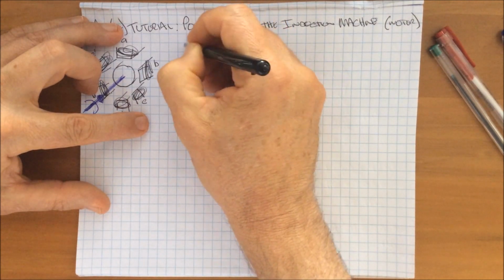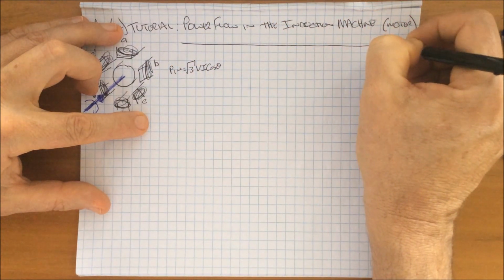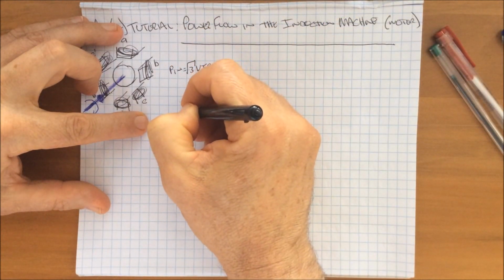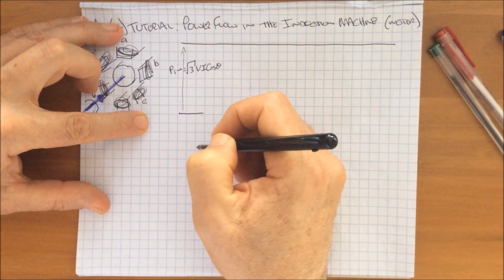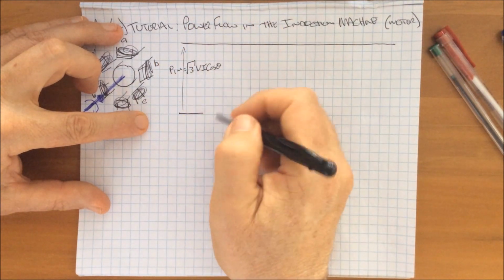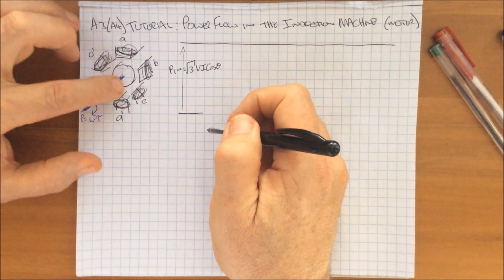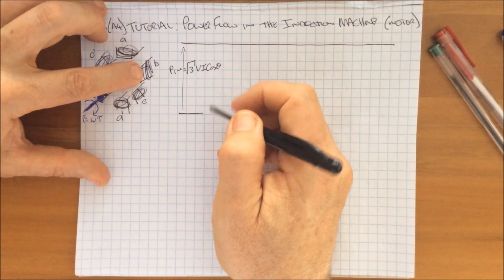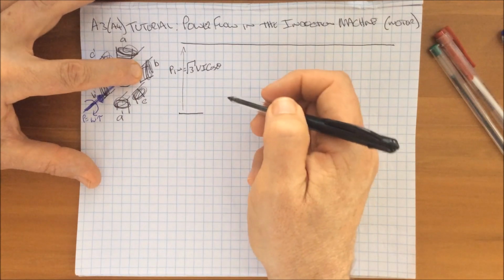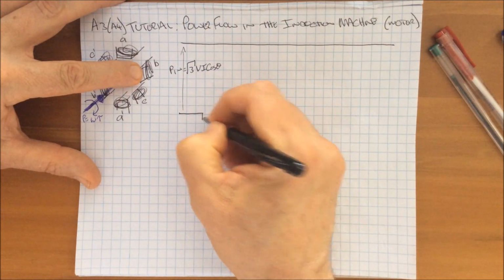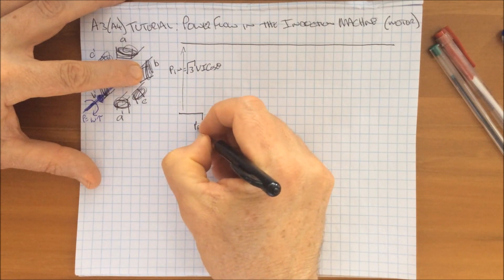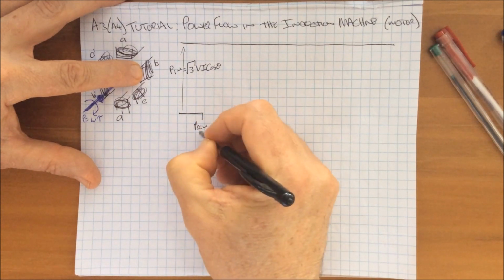So if we draw that out, we start off here, we'll come down here, we'll give ourselves plenty of room. This here is our input power, and we've explained what that is. The first place we're going to lose power when we come into these windings is in the resistance of those windings. And so that is often called the power loss in the stator through copper, PSCU.